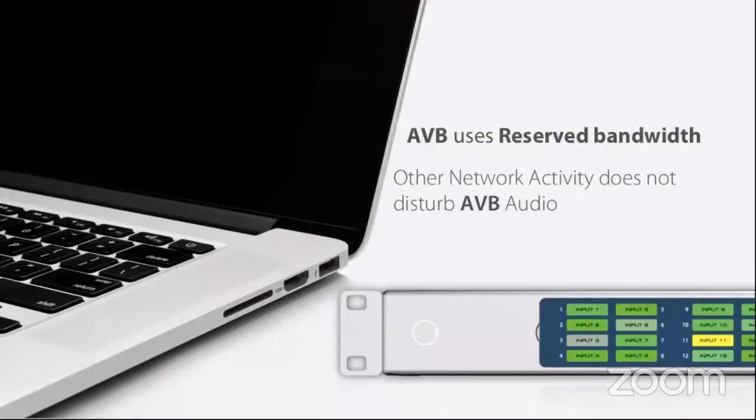Now, AVB uses reserved bandwidth, so other network activity does not disturb the AVB audio. So this goes back to the conversation about the switch. One of the reasons that an AVB compliant switch is necessary is so that we can handle this reserved bandwidth. There might be installations where you have to use an existing computer network that has other network activity on it to also be your audio and video network.